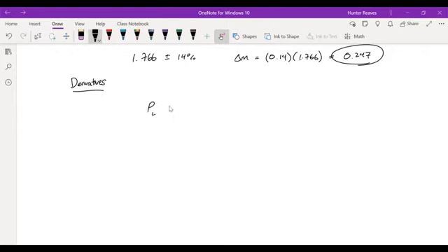But everything I just said, the power being delivered to the load, is governed by this equation here, and that is epsilon squared times big R, which is the value of the load resistor, divided by little r, which is the internal resistance, plus big R, the load resistance again, squared. So this is the power delivered to the load in the case of a DC non-ideal battery, which we'll discuss more in detail once we get to Lab 4. But what we're going to do for this problem is take a derivative of it.